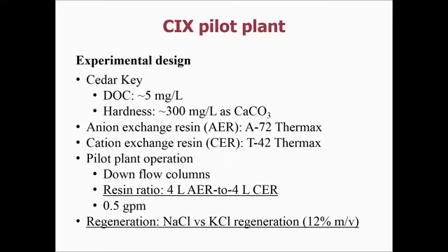And we're doing quite a bit of work on the regeneration side as well. One of the things we're looking at, which is related to some of the other research we're doing and some of the other projects we're involved with, is alternative regeneration agents to sodium chloride. In this case, we're looking at potassium chloride versus sodium chloride, and we're looking at both of these at a 12% solution. I underline the resin ratio and regeneration because those are really the two key things, in my opinion, to understanding and making combined ion exchange a viable process for small water systems.